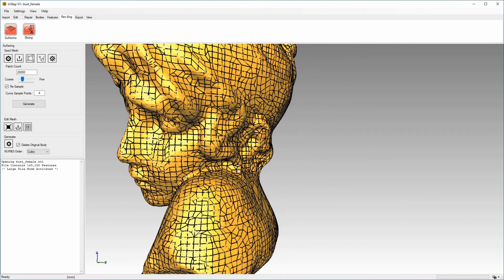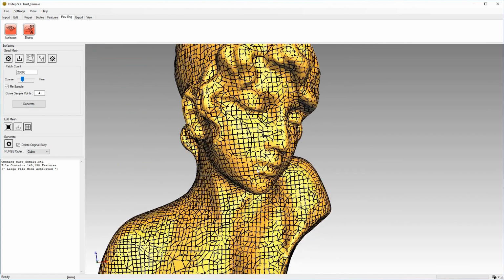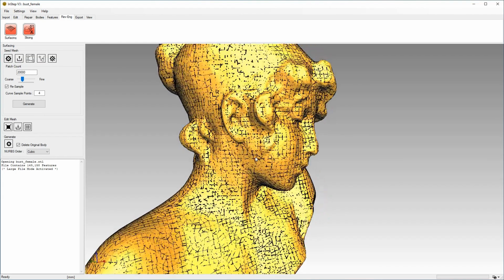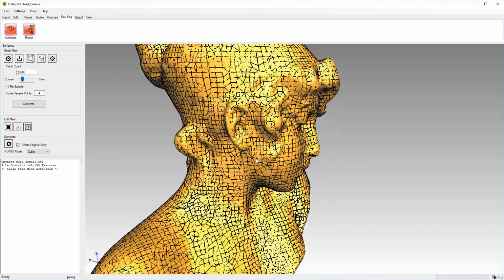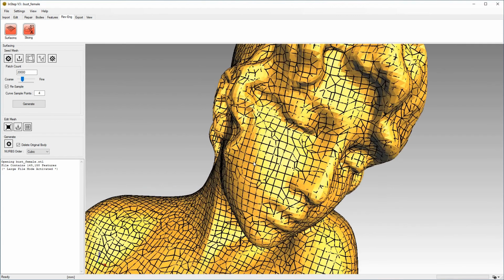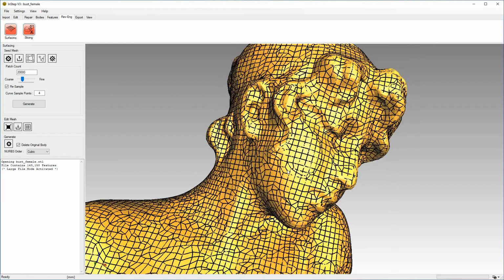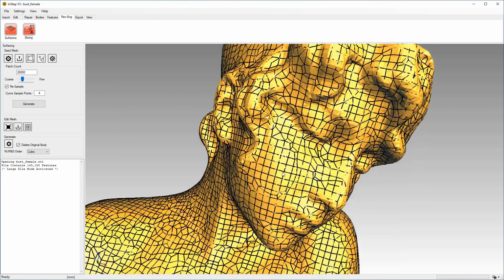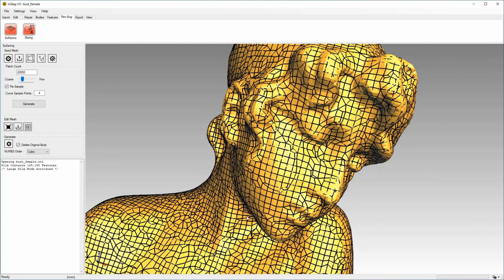we'll see the resultant mesh, and it should be pointed out that obviously the higher this number goes, the longer it'll take and the more memory it will consume. But we often end up then with a mesh that is far more aligned with the coordinate axis, as you can see here. All these facets are a lot straighter and more aligned. So keep that in mind as you go higher in the number.